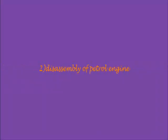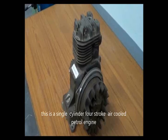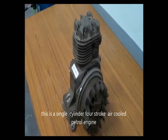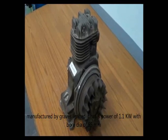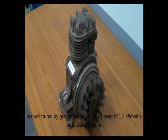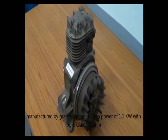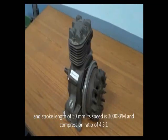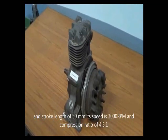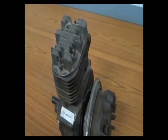Assembly and disassembly of the petrol engine. This is a single cylinder 4-stroke air-cooled petrol engine manufactured by GRIET Limited. It has a power of 1.1 kilowatt with a bore diameter of 55 mm and stroke length of 50 mm. Its speed is 3000 rpm and the compression ratio is 4.5:1.